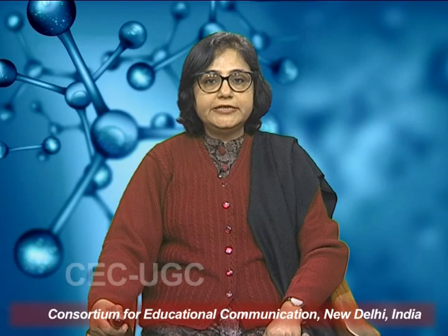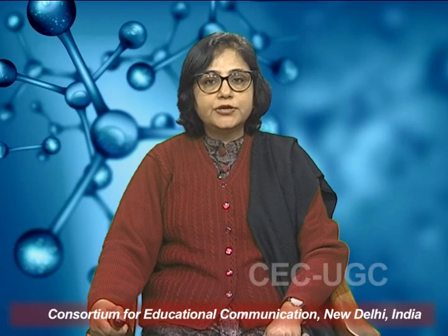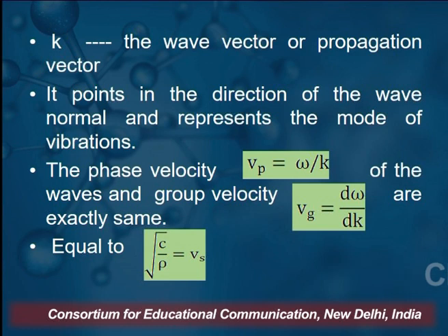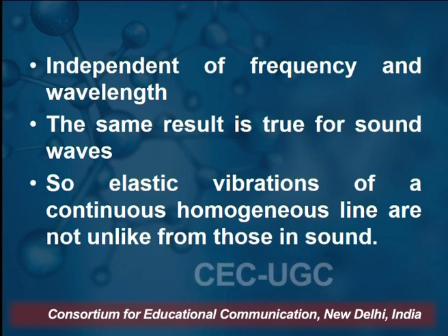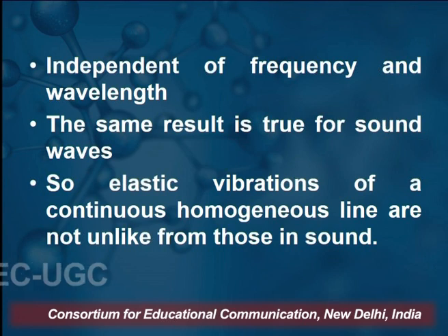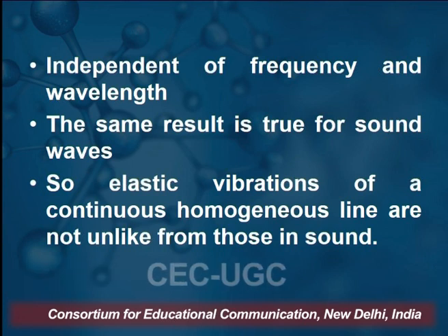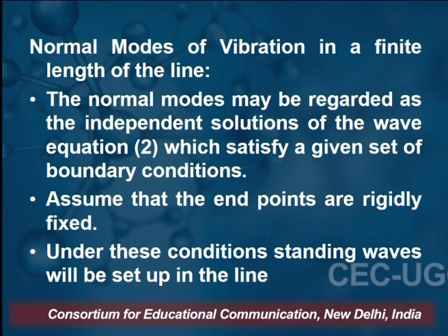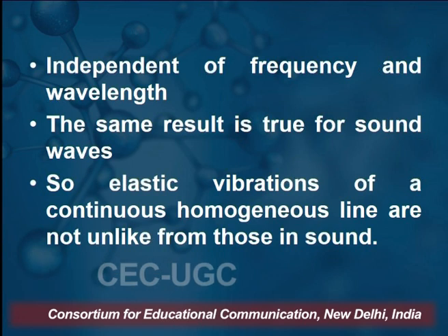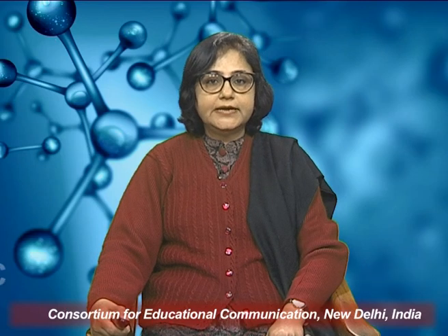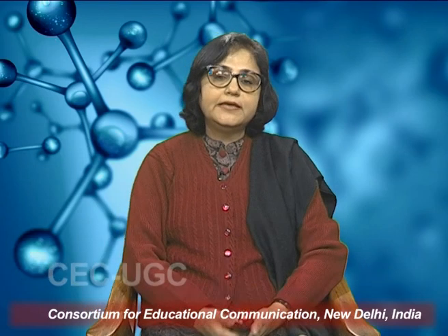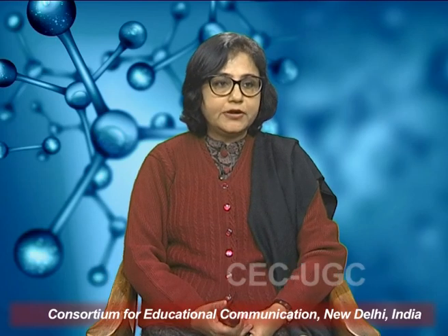My dispersion relation in this case is totally independent of both frequency and wavelength. That means the wave that is propagating through the system is a sound wave. Elastic vibrations are sound waves that are propagating through the material. And the phase velocity and group velocity are the same, equal to under root of c by rho.